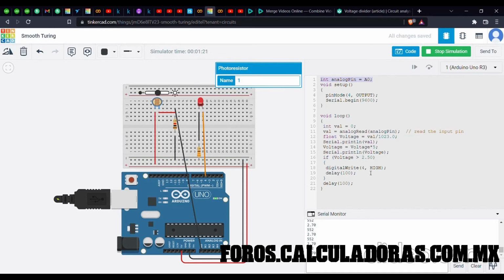Okay, so that is done by this logic here, and you can see this line of code is actually reading the analog input here, then I am dividing it by 1023 and then I am multiplying it by 5. Ignore the serial print line of code.